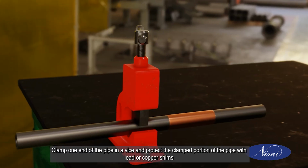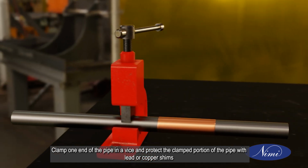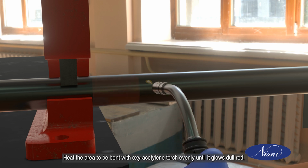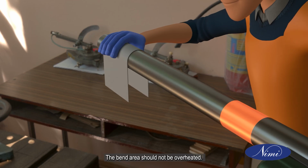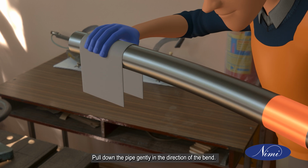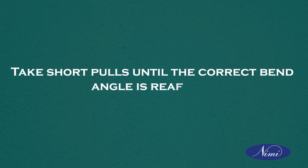Clamp one end of the pipe in a vise and protect the clamped portion of the pipe with lead or copper shims. Heat the area to be bent with oxyacetylene torch evenly until it glows dull red. The bent area should not be overheated. Pull down the pipe gently in the direction of the bend. Take short pulls until the correct bend angle is reached.